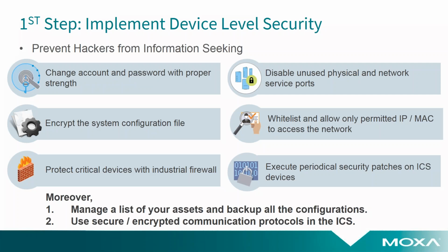So looking at those things in a little more depth, again, device hardening. A lot of these are things that a consultant can come in and do for you, or you could do with part-time employees: changing account passwords, using stronger passwords, disabling the unused physical and network service ports, making sure that you're encrypting critical files and encrypting connections to the management interfaces, whitelisting and allowing only permitted IP or MAC addresses to the network, protecting critical devices with industrial firewalls, and executing periodic security patches.